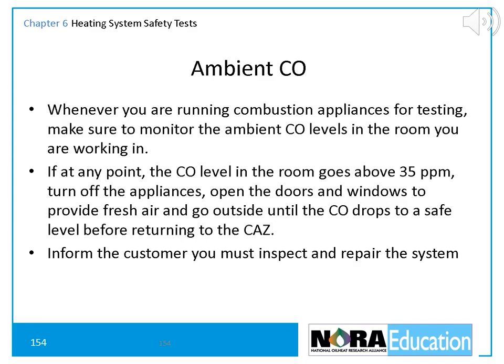Ambient carbon monoxide. BPI certified contractors are trained that whenever they are running combustion appliances for testing, to monitor the ambient CO levels in the room in which they're working. If at any point the CO level in the room goes above 35 parts per million, they are instructed to turn off the appliance, open the doors and windows to provide fresh air, and then go outside until the carbon monoxide drops to a safe level before returning to the CAZ. We should be doing the same thing. When the ambient air goes above 35 parts per million, the home performance contractors are supposed to tell the customer that they should call a heating technician to come and inspect and repair the system. That's when you get involved.